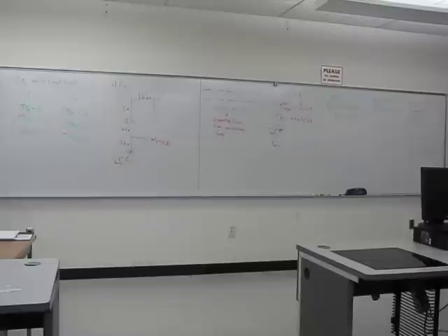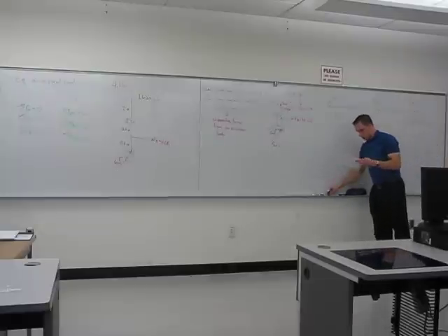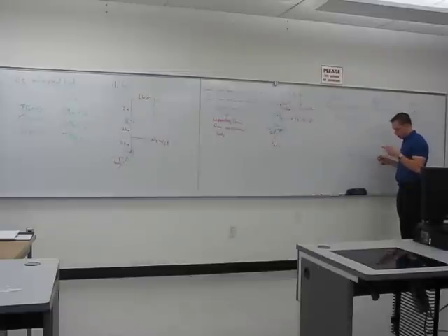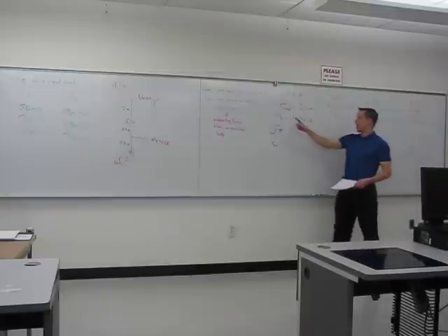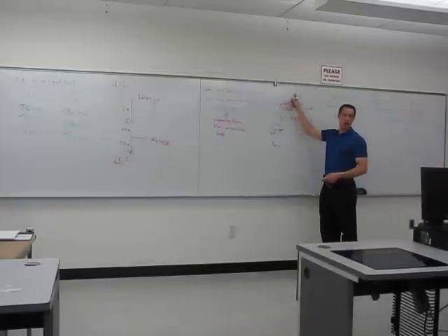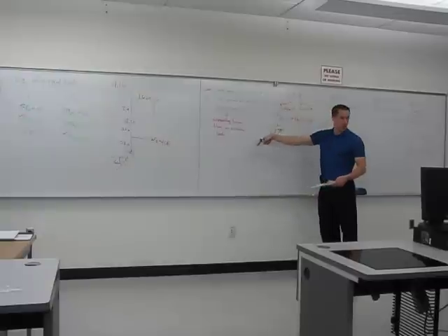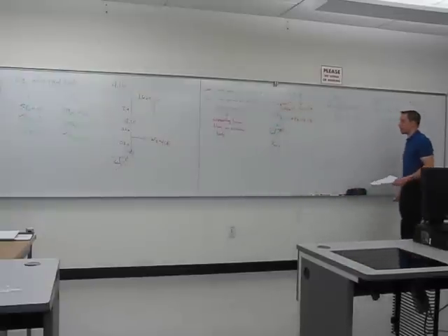So I didn't really have to worry too much about my guess because now I know which way it really is. FCY, when we solve that one, we should get negative 0.93. So again, I guessed up for FCY, but in reality I got down. So the net result here is I assumed that FC was in the first quadrant. But my 2 minus signs tell me that it's actually in the third quadrant. Okay, fine, I know that now.